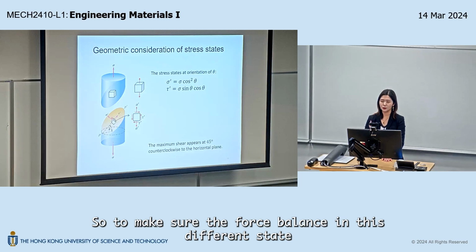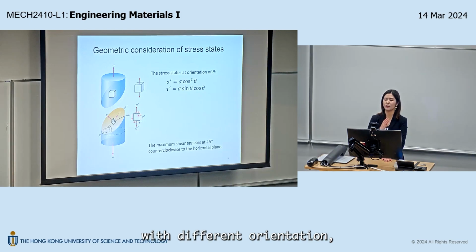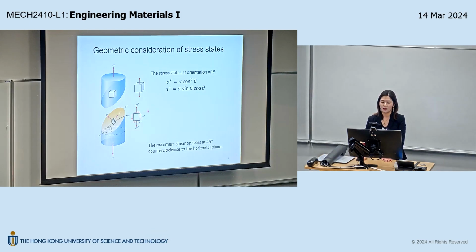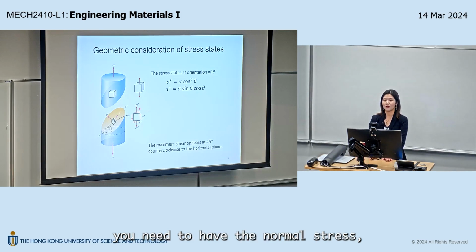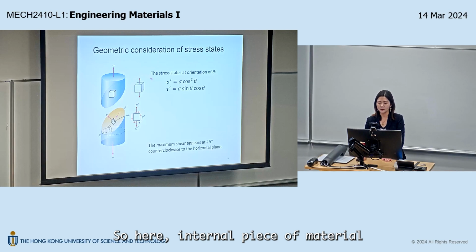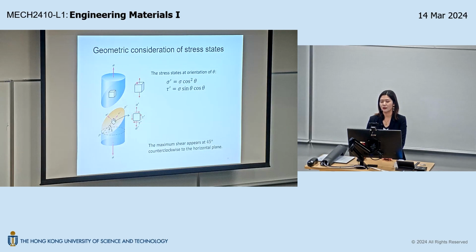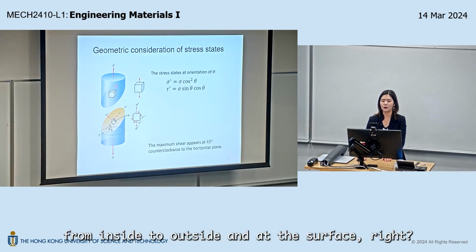To make sure of force balance in this different state with a different orientation, you need to have the normal stress, which is sigma prime here, with a different value. The internal piece of material should be in equilibrium everywhere, from inside to outside and at the surface, right?